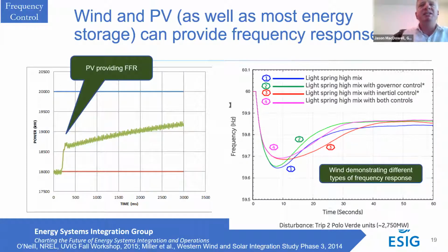And those capabilities we can see here in another study we had done together with the Department of Energy and NREL to show that the fast frequency and primary frequency response enabled out of wind and solar generation can actually support the system better than having the synchronous assets alone, as long as they're coordinated and you have the capability to arrest the decline with the fast frequency response and recover in a controlled fashion with primary frequency response that you see here on the right.